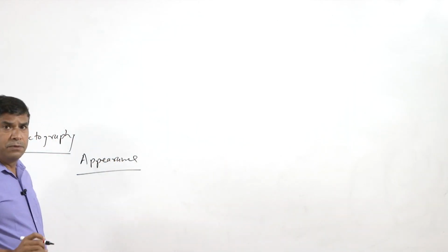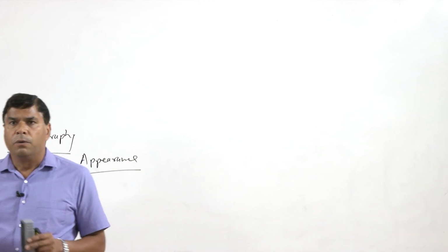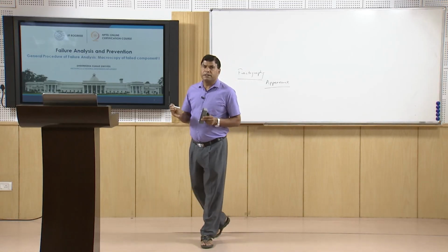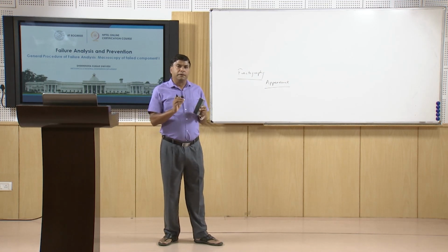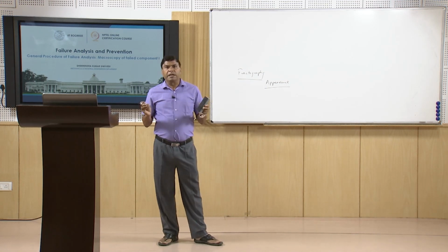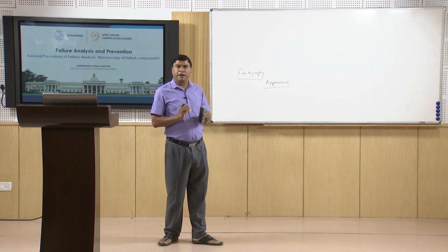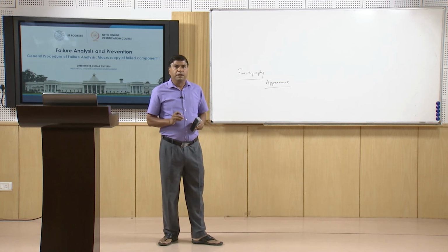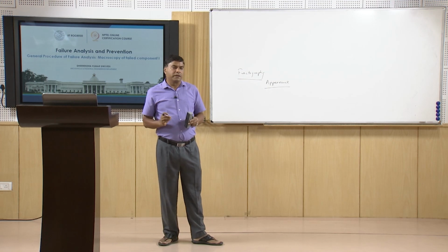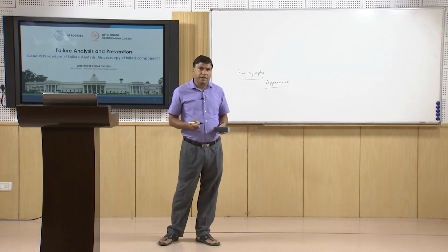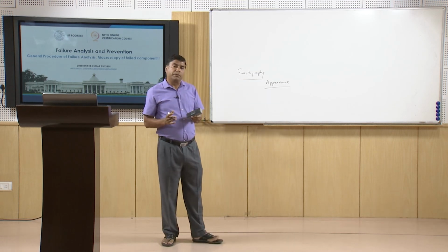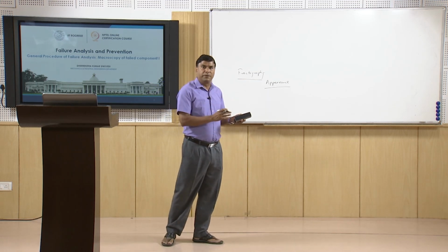These include the ductile fracture, where significant plastic deformation of the failed component takes place. The brittle fracture, where there is no indication of deformation prior to the fracture. The fatigue fracture, where the fracture surface shows the typical appearance of beach marks, indicating that the component has been subjected to fatigue loading.